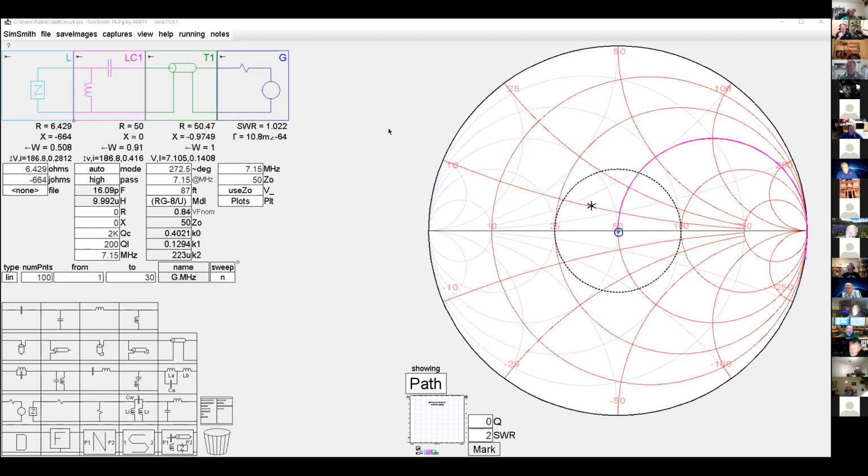It's very true. Many years ago, in engineering, we used to be concerned about the new engineers that were coming out of school, because they didn't have a feel for things. They'd put numbers in a program and come out and tell me, well, that's 100,000 amps of fault current. I go, okay, yeah, but do you know how much that is? Do you know how much that is relative to what's considered to be normal? There's probably not a circuit breaker on earth that's large enough to break that amount of current.